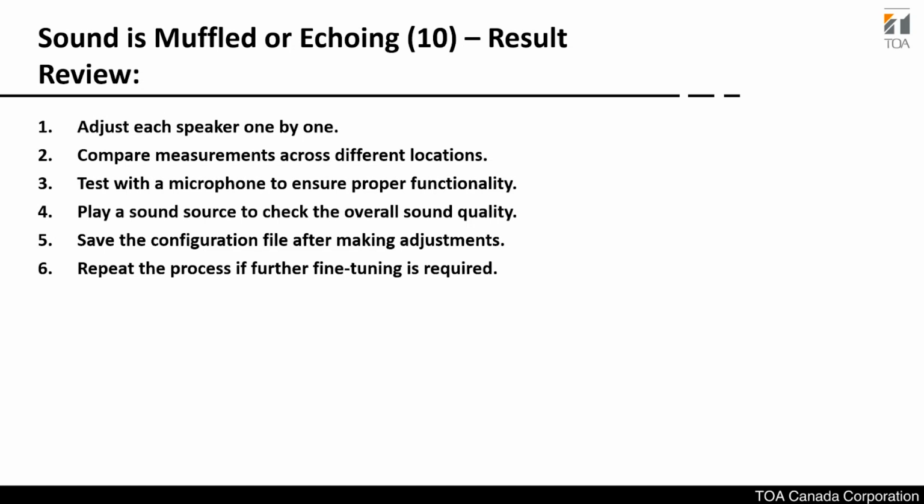Adjust the speakers one by one. As in our example, we start from the right-hand side first, and then we do the left-hand side. Compare the measurement across different locations. Sometimes if you have more than 2 speakers, you can place the smartphone with the app closer to the speakers, test the microphone, and play a sound source according to the overall sound quality. And remember to save the configuration. Repeat the process if further tuning is needed.